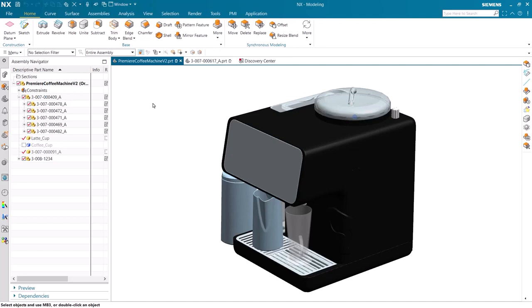The NX MBD rules provides rapid definition and authoring of product manufacturing information, or PMI, with an emphasis on capturing knowledge and company-specific business logic. You can use your choice of the over 100 available production-ready out-of-the-box MBD rules, or when necessary, define your own that complies to your specific business needs. Rules leverage topological feature recognition that also enables support for authoring on multi-CAD data.